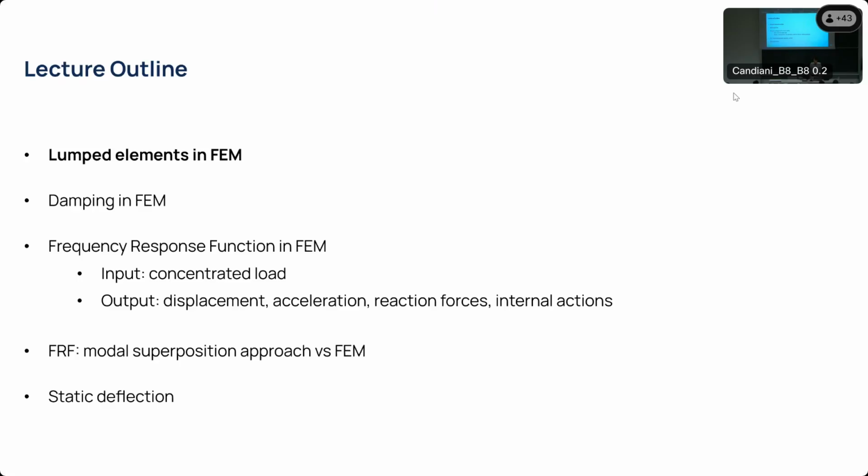So during the last lecture, we will also be able to go a little bit in depth on what you need to do for the assignment. So today we are doing basically 4 things. So actually 5. We are introducing lumped elements. Last time we saw how to compute the mass and stiffness matrices for distributed elements, the same things you saw in classroom. We will see how to introduce concentrated springs and concentrated masses. Then we will see how to model damping. So for now, structural damping, but some of the considerations we did for lumped elements will also be used to discuss concentrated damping. And then we will start looking at frequency response functions.